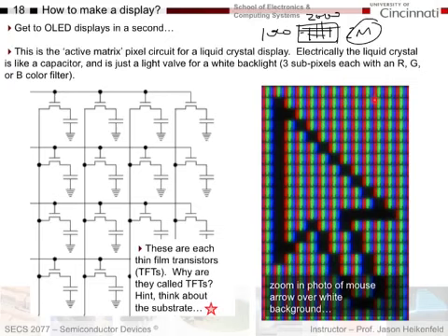And so what you do instead, you use something called active matrix addressing, where each pixel is a capacitor and is at the intersection of multiple columns and rows, and each intersection forms a pixel. So this is kind of like when we had memory, remember? It's a very similar design where basically I have a transistor for each pixel. So this is the pixel here, this is the pixel, and this here is the transistor. So that's my transistor in this case. And if I want to write this pixel and only this pixel, I will put voltage on this row, which turns this transistor on and only lets voltage coming up this column to then set the pixel level to a certain level of black or gray in terms of its transmission, black or white in terms of its transmission.